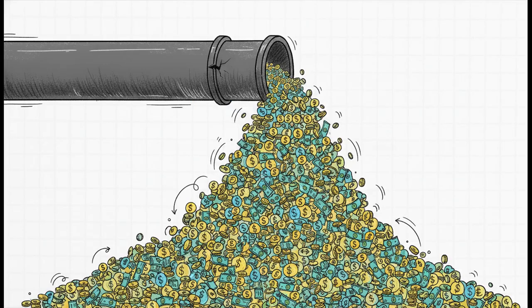Now, I really want to hammer home why that top row matters so much. If you have a basic low-voltage setup, you might only have 1 or 2 secondary cores because, frankly, the stakes are low. But when you're measuring power for a massive 132 kV industrial customer, you must use a highly precise Class 0.2 measuring core. Why? Because you are selling massive volumes of energy. We're talking millions of watts. Missing even a tiny fractional percentage of those megawatts because of an inaccurate CT core translates directly to a huge loss of money. In this business, precision literally equals revenue.